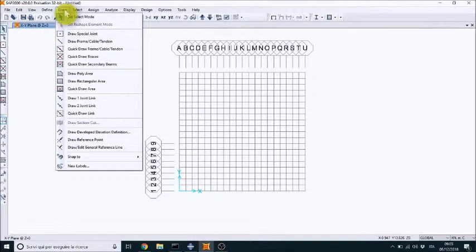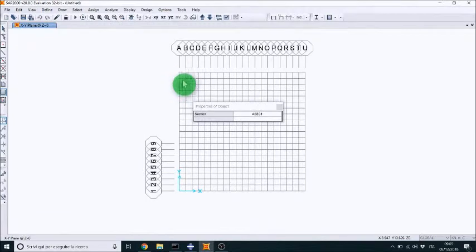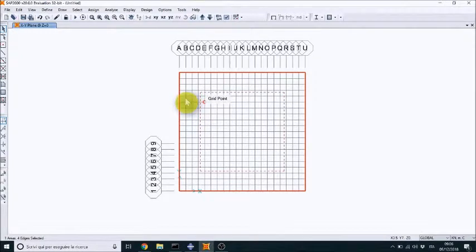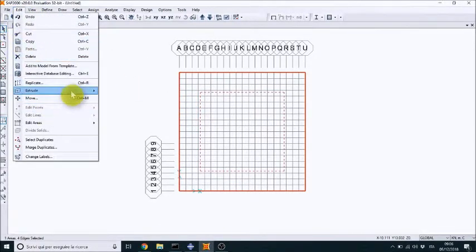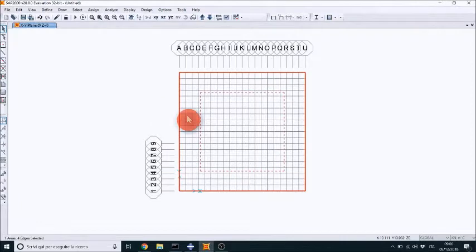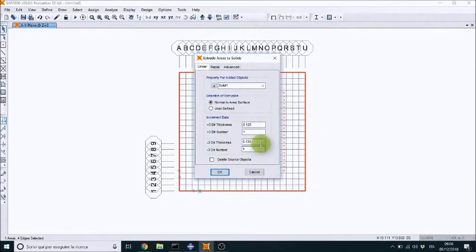Okay, we can create a rectangular area and perform an extrusion of this area. I'm going to extrude only, of course, in the positive direction, 10 meters in one time. So only one element, 10 meters of extrusion.